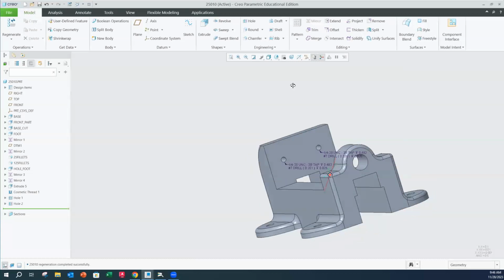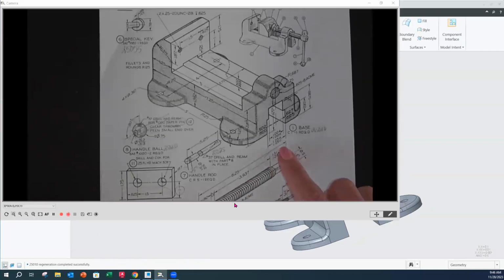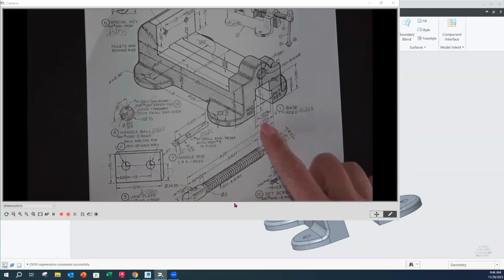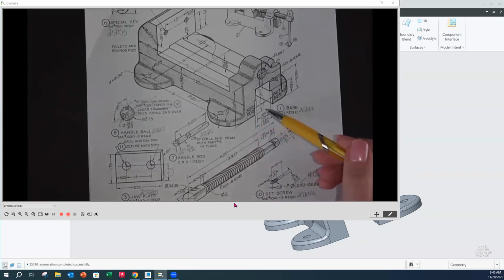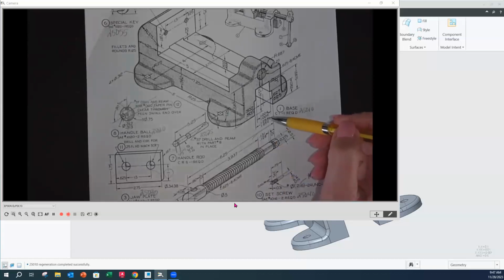Now the next thing I wanted to talk about is the width of the cutouts on the bottom here that are going to be utilizing tolerances when it's in the drawing mode. I'm going to go back over here, and we're going to look at the values we have for each one of the cutouts. The width on the widest part is 1.254 to 1.250. Those are the limits. That means it can get as high as 1.254 and as low as 1.250.